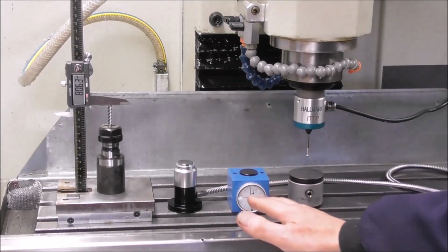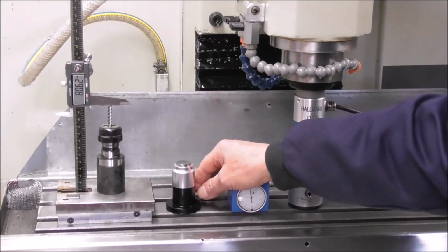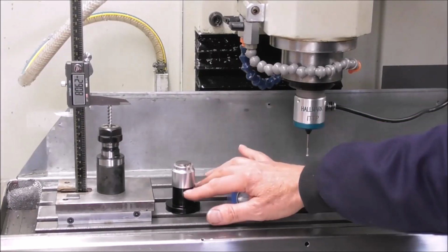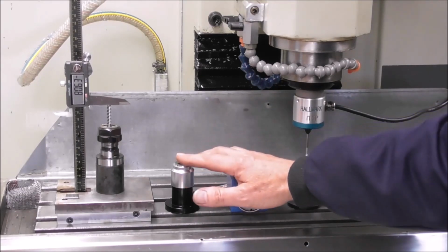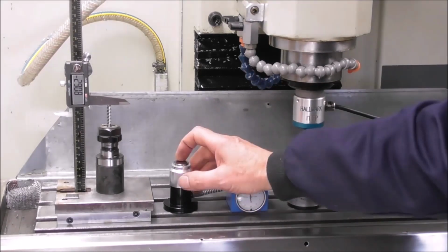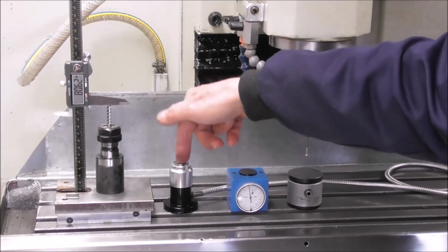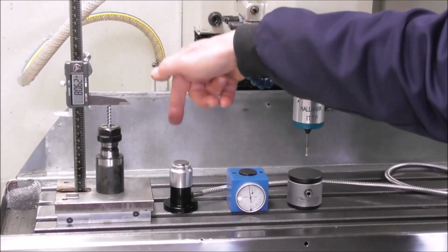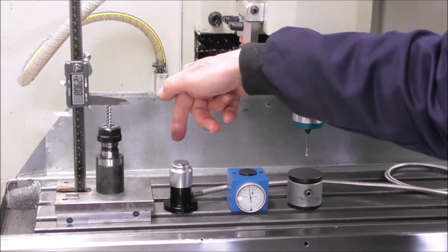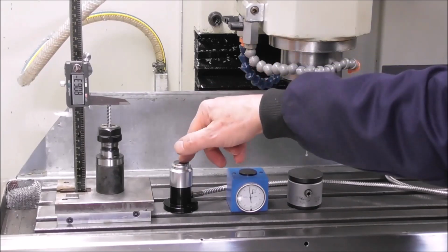There are problems with each one and advantages with each one, and I'll go into those more deeply in a moment. But it would seem on a quick cursory glance that the electronic tool setter is the best option. It's the most sophisticated because the software will automatically do the work for you. There's a downside to an electronic tool setter, an automatic tool setter, because you're bringing your tool down, and that might be an expensive tungsten carbide tool that comes down under a tool length setting probing routine and sets the height into the tool table.